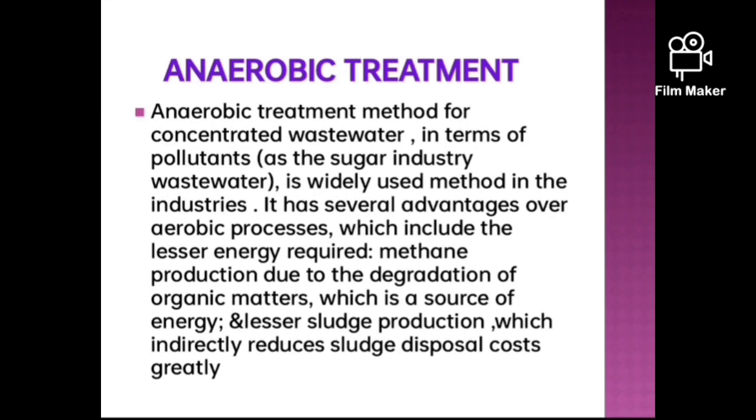It has several advantages over aerobic processes, which include the lesser energy required, methane production due to the degradation of organic matters, which is a source of energy, and lesser sludge production, which indirectly reduces sludge disposal cost greatly.